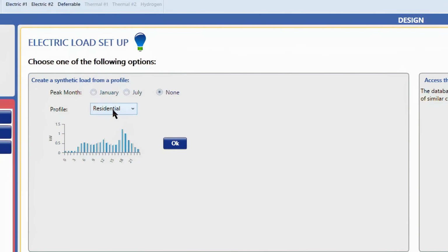Okay, so the first part that we are going to see is this rectangle here. There are some default loads, or default load profiles, which are already implemented in HOMER. If you want to run a quick and short simulation, we can just choose one of them. It's easy. It is already implemented, all the numbers are already inside, and we don't need to enter any load amount into the program first.